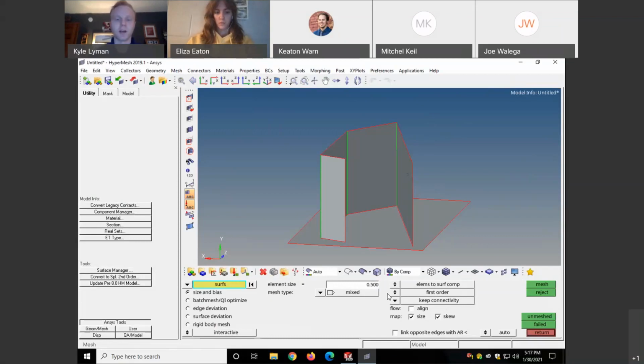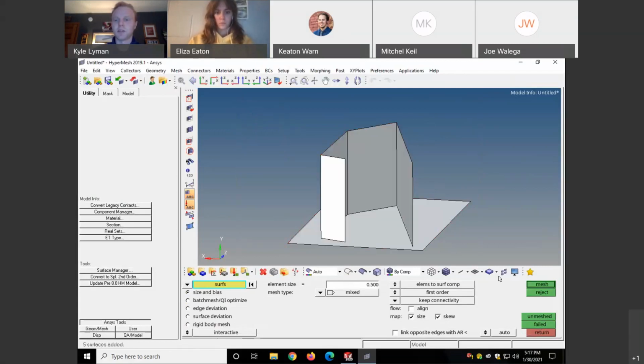And you can look more into the element size and what that unit is if you want to know more about it. And I'm not going to change anything here. We're just going to match it by the size. And that's what we just entered here. These are not important for what we're doing right now. And so we're going to go ahead, click on this. We're going to hold down the Shift key and the left click, or draw a box around all the surfaces here. And you can see it's highlighted them right there.